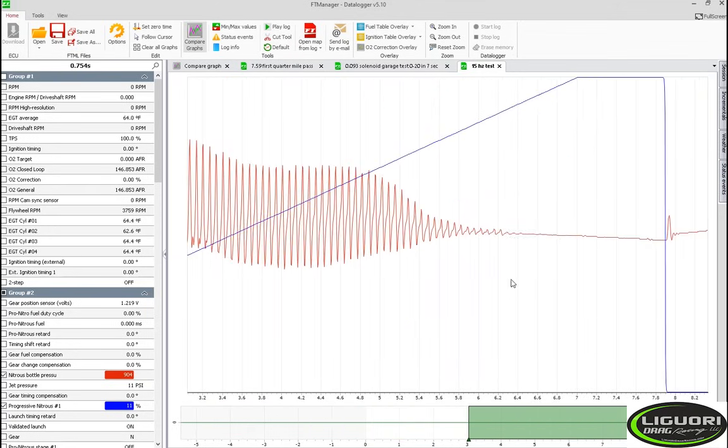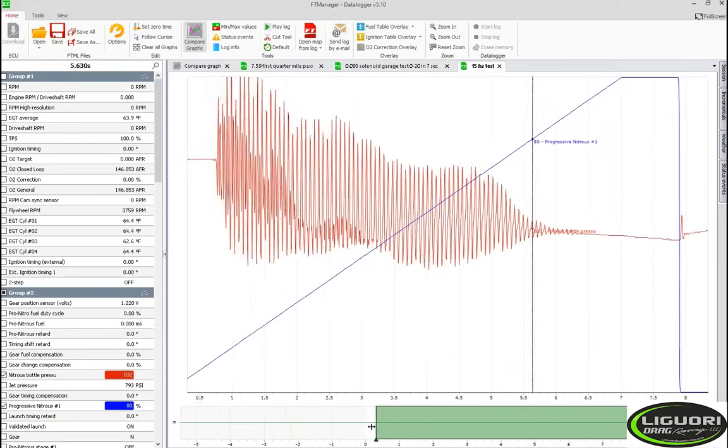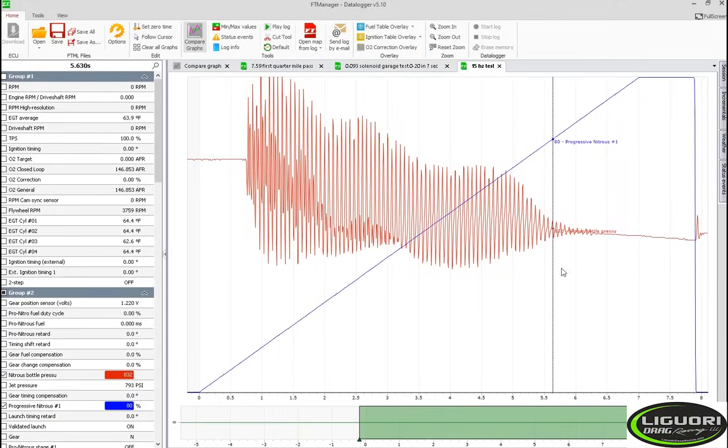And you can see at the end here, when the nitrous levels off, it levels off pretty much 100% right here. You're at 90%. This isn't really doing much anyways either. So if you look at 80%, you're not pulsing the solenoid that much. So just have all your fuel in by 80% at least. And that way you can keep your engine safe. But when you're doing a ramp down the track, you can see where your solenoid opens and when it closes.